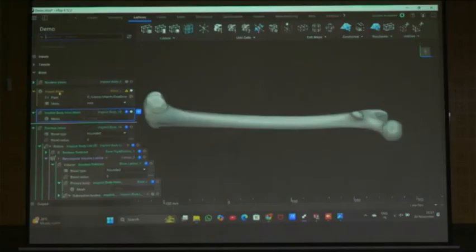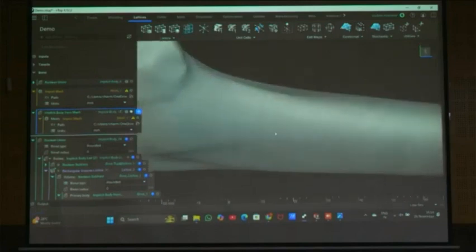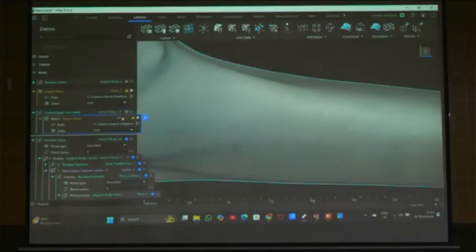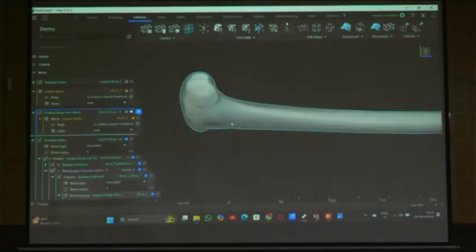So I will import this one, I will drag this one. You can see here, as I told you, there is a globe symbol, a network symbol, and here also a globe symbol. So this will accept it, or otherwise double click on it, and the available options will show, max underscore 1 name. Okay, you can get this one. See, it converted into an implicit body. Previously our body was like this, now our body is like this. So now we can do whatever operations we want.